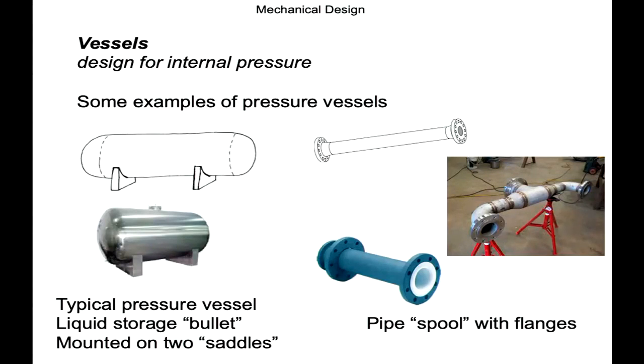We put a gasket, a soft material, where I'm waving the laser now, then put the flange of the next component against it. We hope all the holes line up and we bolt it all together and provide a friction grip that distorts that gasket a little bit to stop routes, pathways for which the pressure can escape. But nonetheless, just because it's a pipe doesn't mean it's not also a pressure vessel with all the associated weaknesses at these discontinuities that you might expect.